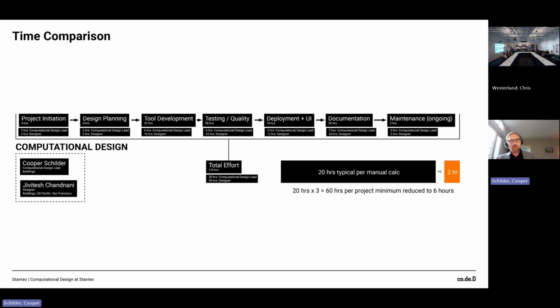So this script takes away some of that potential for manual errors while also speeding up the process considerably. And by adding in that ability to jump room by room and do a double check, that can catch any of those issues that might pop up from the script not potentially reading the geometry correctly, or if there's something that was encoded in the Revit model improperly, or sometimes people model things not according to the standards. So this allows people to do that quick double check while also making sure that you're getting quality results.